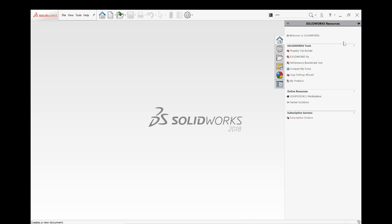So you have SolidWorks Resources over here. You can do a performance benchmark test or SolidWorks RX. Sometimes when Windows updates, you can't even sketch a line. I had this problem where every time I tried to sketch, it would just crash on me. So what SolidWorks RX does is bring up a couple of modes, and you can go in safe mode so you can still use the features. It won't be the same as what you have originally, but it's great for troubleshooting.